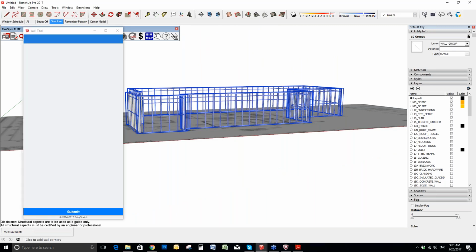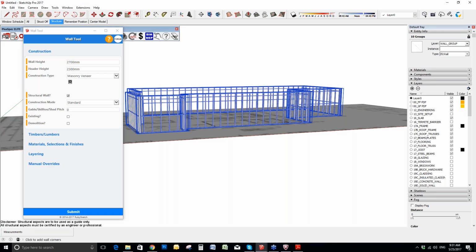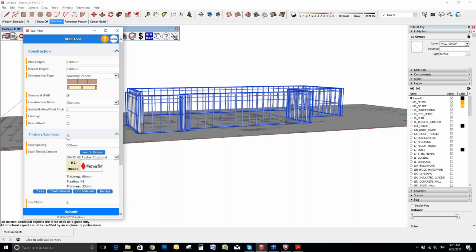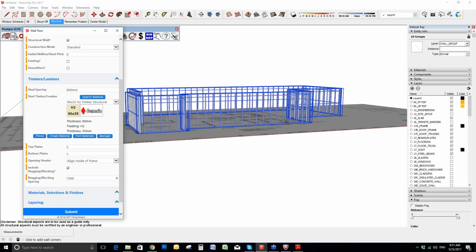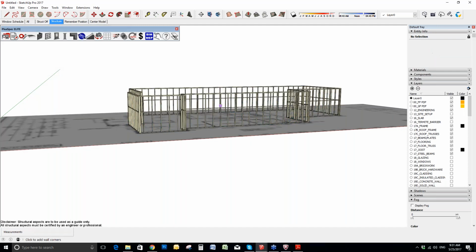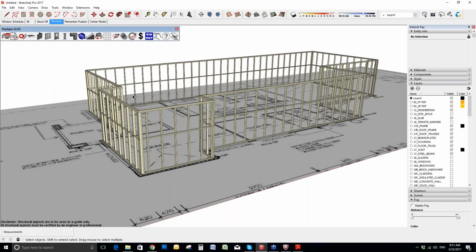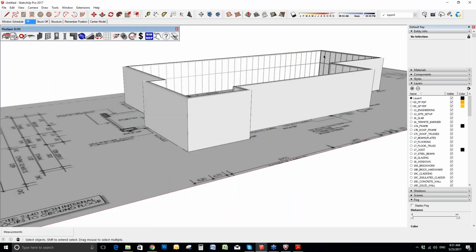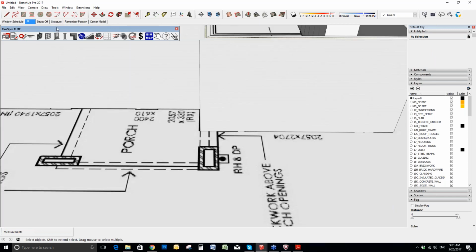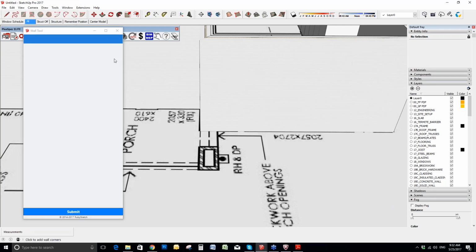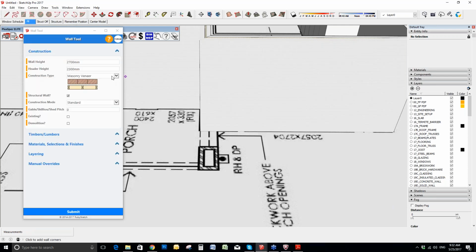What I'm trying to show you here is that although you might start drawing, the PlusSpec tools are so flexible and parametric, which means you can modify them at any time. For example, I've changed my nogging spacings, and I can do whatever I want there. I can go back through the different scenes because they might help me model smarter and faster. If I wanted to be dead accurate with my gauge, I could also put down my grid, set it to my brick gauge, and make sure it's even working to brick. But again, for an estimate, I don't really care.